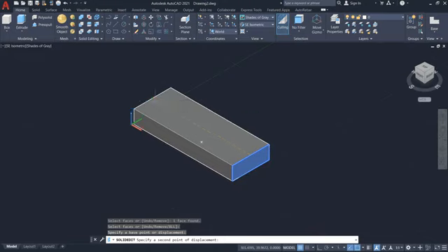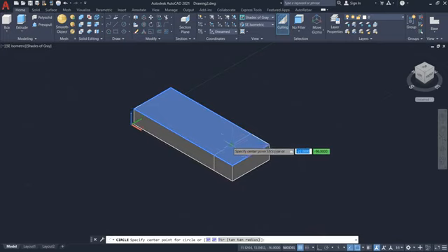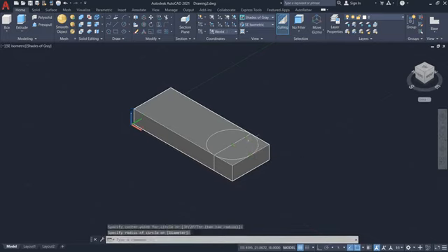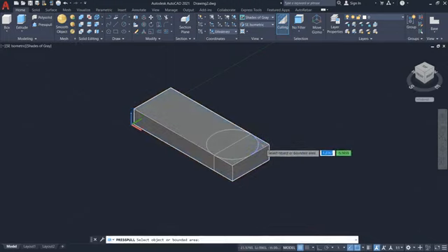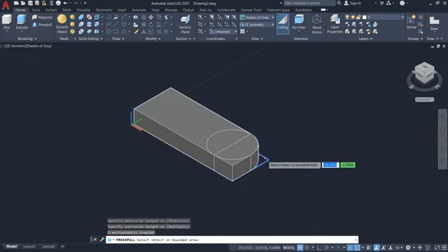So I snap. Why? Because it comes in the linear position. So now I will enter 22. Okay, exit. Now I will draw the circle whose diameter is 44. Here I have selected the center point. I will select at the edge. So here is the circle of 44. Now at the edges I do not need this part, so I will just select press and pull. Select this outside part and go down. You can see now the outside part is deleted. So again I will select this part and go down. You can see this part is also deleted.